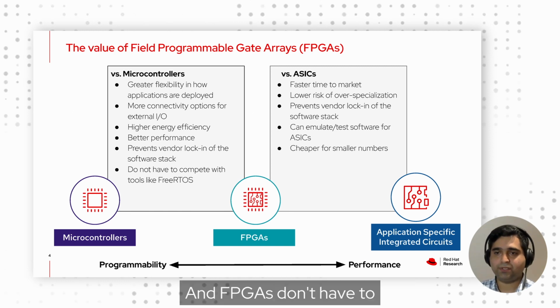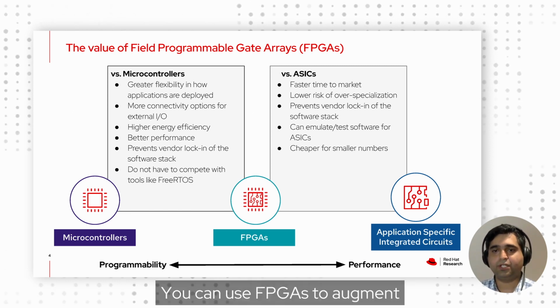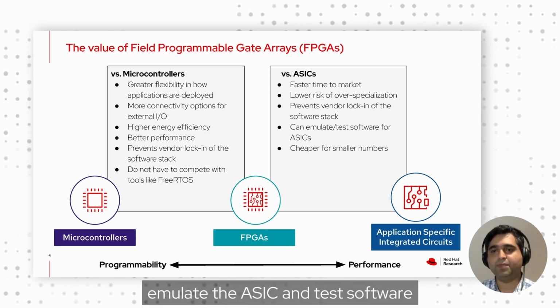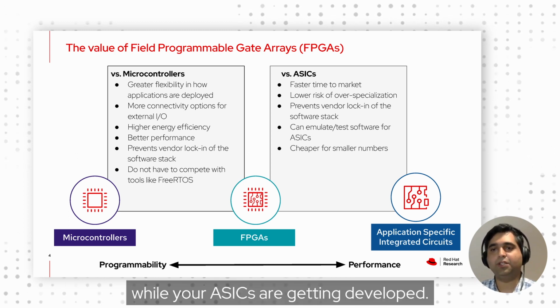And FPGAs don't have to replace ASICs entirely. You can use FPGAs to augment the ASIC development process by using FPGAs to emulate the ASIC and test software while your ASICs are getting developed.